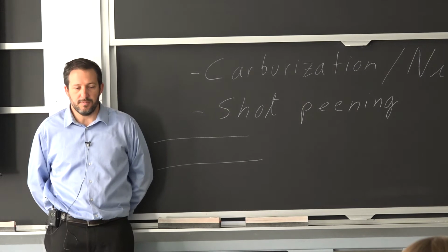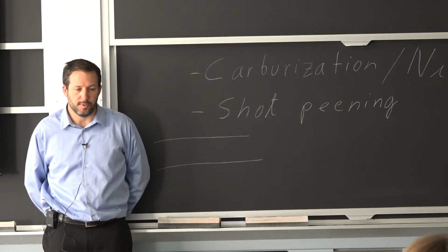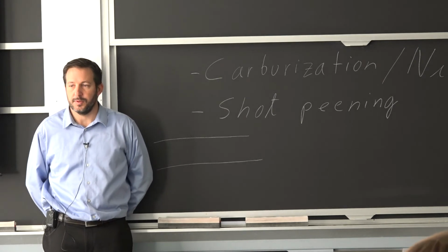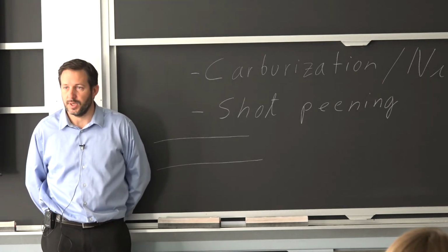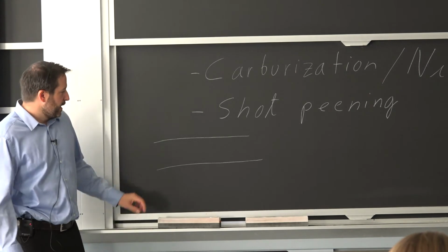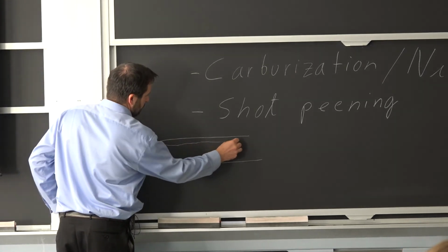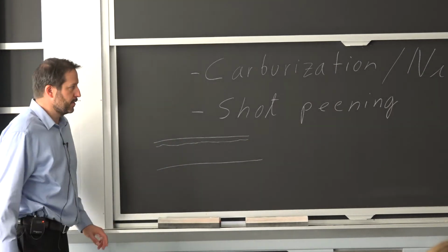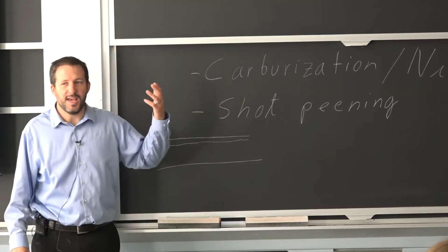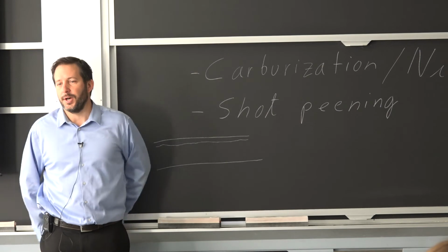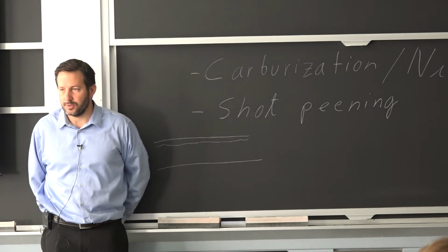So it's an effective way. It's used for helicopter blades and a lot of aircraft components. Some of the drilling equipment goes through this process as well. Depending on the size of the bead, you can specify a certain depth to this deformation layer. In this case, it's really a mechanical way to work the surface so it's in compression.